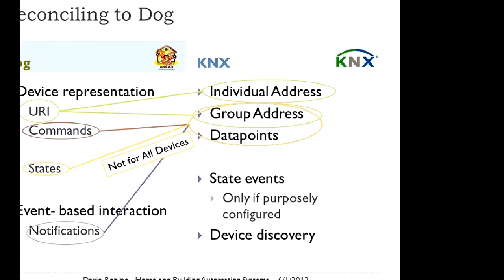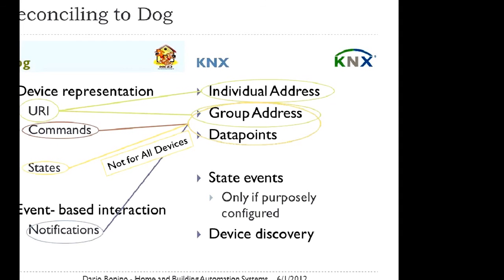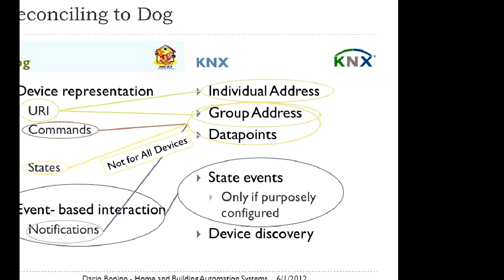Maybe we can listen to the notification. Because if we correctly set the binding on the button, an open binding, then we listen to the message sent by the button data point. So we have the state change notification for the button. And we need at the driver level to bridge, to fill the state using this state change notification. Okay? So we can still get the states for all the devices, but the complication is higher. And even this interaction can be easily obtained if we configure correctly the plant.